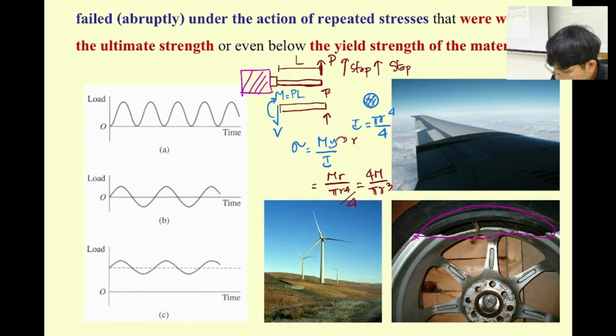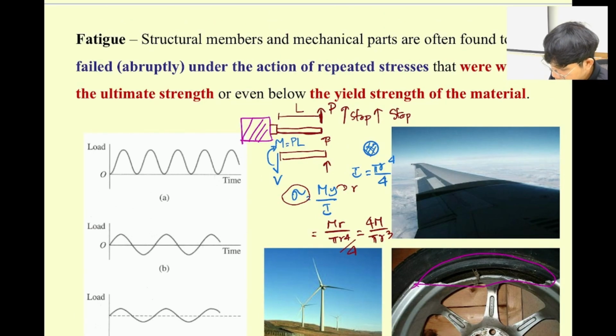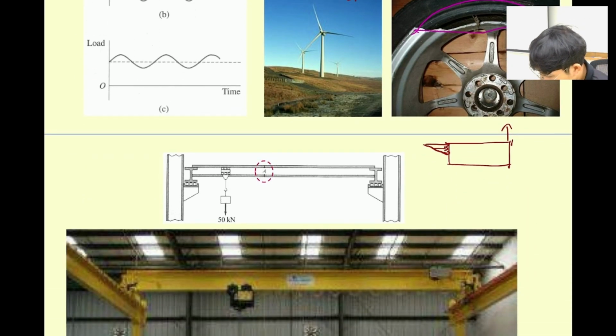And then what is the stress over here? Okay. If you remember from mechanics of materials, if we have the surface over here, when you have the P pulling up like this, there will be some compression force on your section. So this one is your sample, right? And then you calculate the stress for the sample. There will be some compressive force over here, and then there will be some tensile force occurring over here.